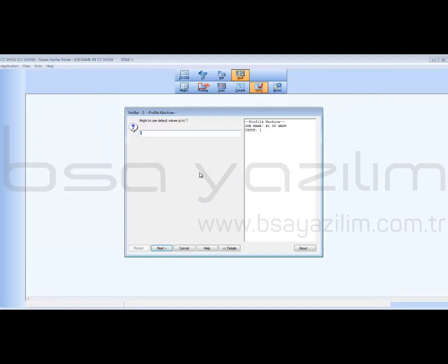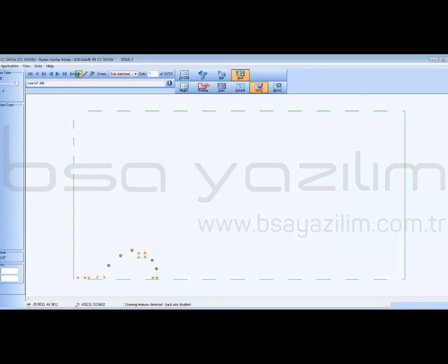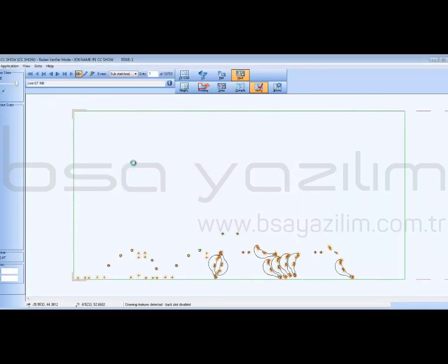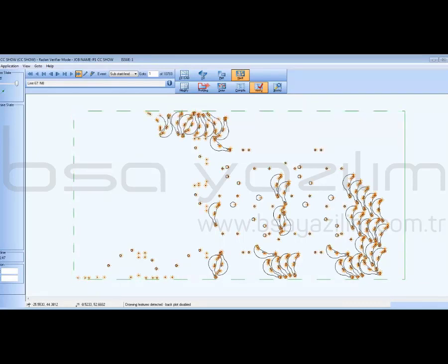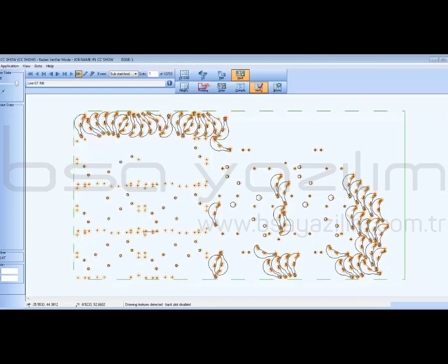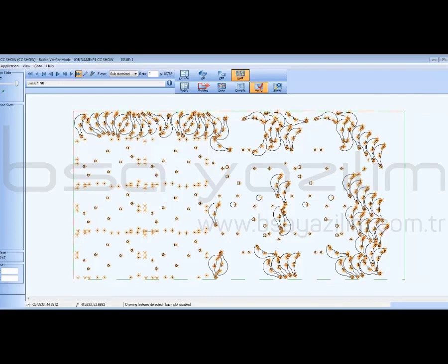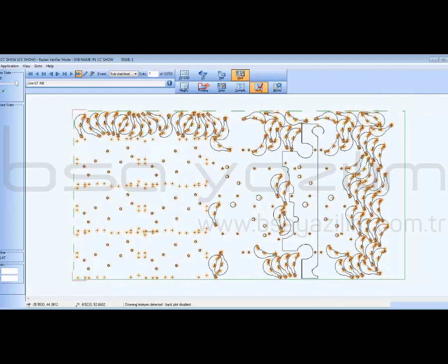Notice how the holes in the parts that will be common line cut are being cut all at once instead of just per part. Also notice that the small part that is not common line cut is cutting in typical part order where the holes for each part are cut, then the outsides of the small parts. The last things cut in the nest are the external profiles for the common cut parts once all the holes for all the common cut parts are cut and any other parts in the nest.